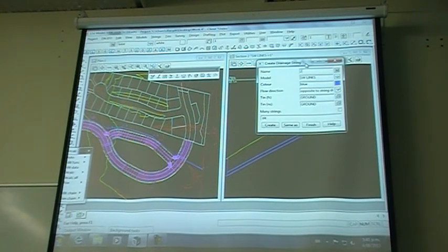just like road centre lines, the model has to be the same for all of these drainage lines. It has to recognise that the naming convention for the model is the same. Otherwise it won't recognise that all these parts of the network are interrelated. So my stormwater lines I put into a model called SW lines, and wastewater I put into WW lines.